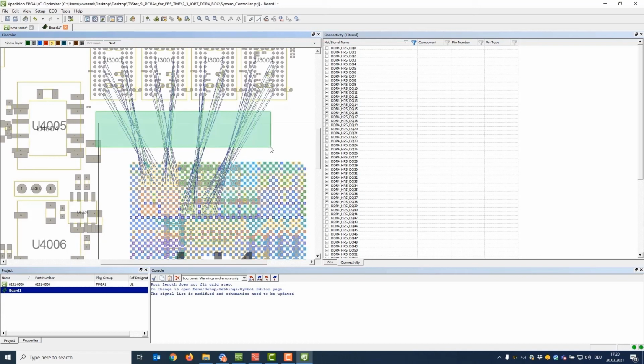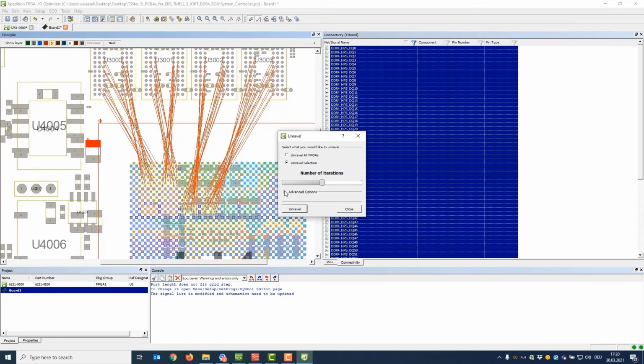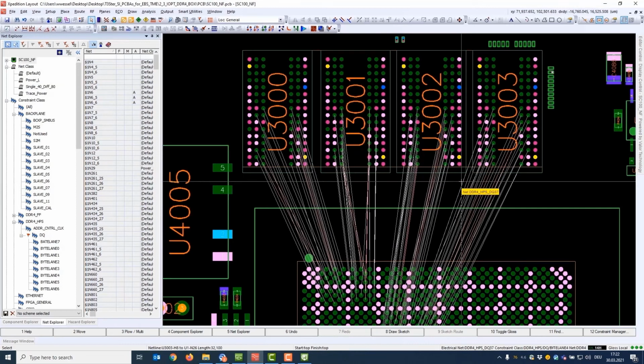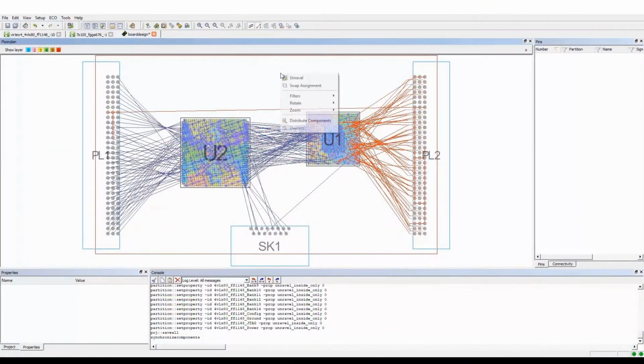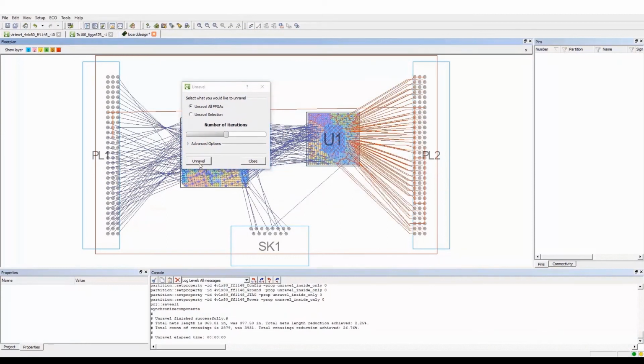These groups can be treated as separate HDL entities within the tool and can be created manually or extracted from an HDL file. During the component placement and orientation on the board, floor planning using the FPGA-PCB co-design can be done before and during the PCB layout process.